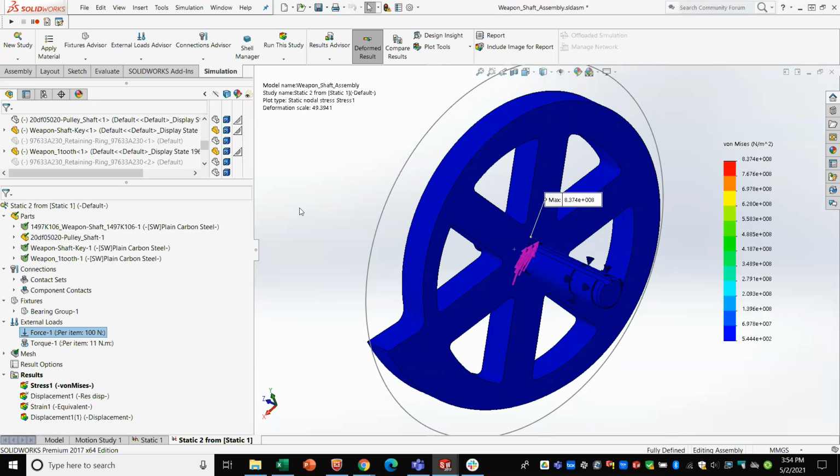So this is where you have to couple knowledge of FEA with experience in the field. FEA will never tell you everything that you need to know up front, because it's always predicated on what you put into it. In this example, I have given 100 newtons of force on the tooth. The force on the tooth is going to be orders of magnitude higher when you impact something. Yeah, of course. It could be upwards of 6,000 newtons or something, or even more.